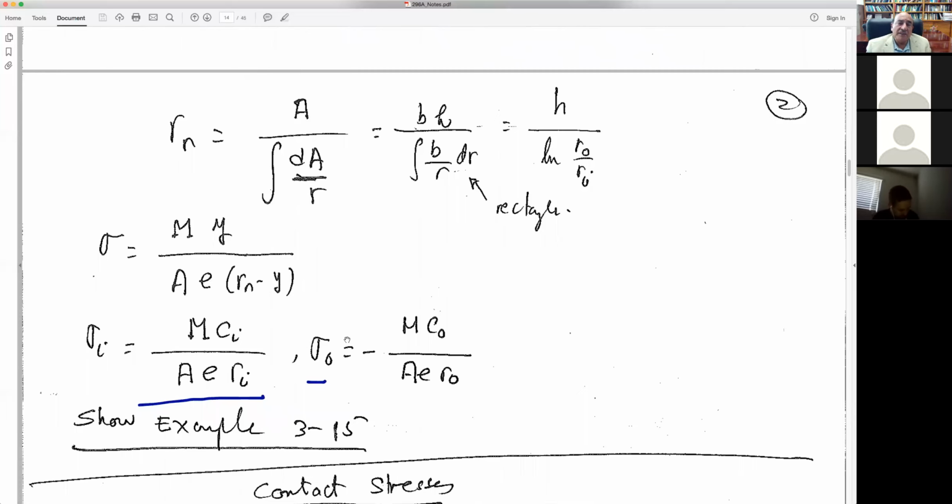And usually we have an additional force. What we have here is a stress due to a pure moment. But in the applications we have, there's always going to be an axial force in addition. So if I have a hook, there's going to be the force that has to be transmitted in addition. That force can give you tension that is very simple, the force divided by the cross-sectional area. So you don't forget about this contribution as well.